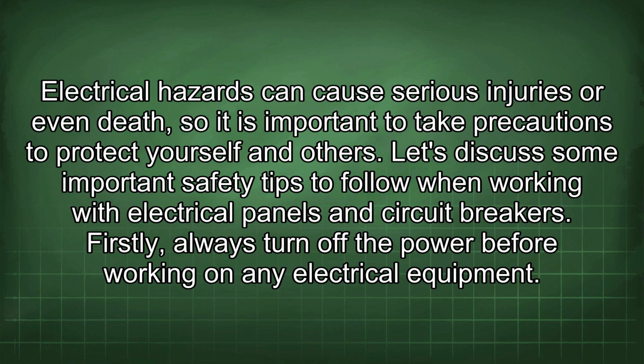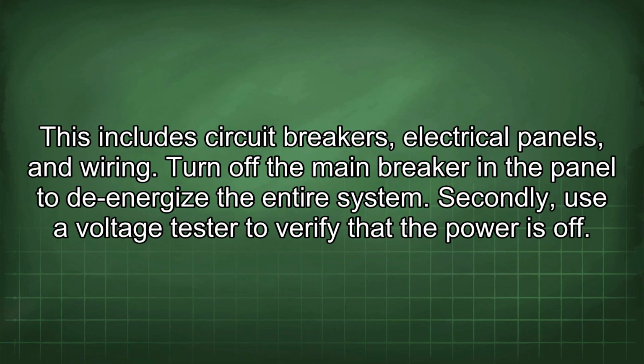Firstly, always turn off the power before working on any electrical equipment. This includes circuit breakers, electrical panels, and wiring. Turn off the main breaker in the panel to de-energize the entire system. Secondly, use a voltage tester to verify that the power is off.